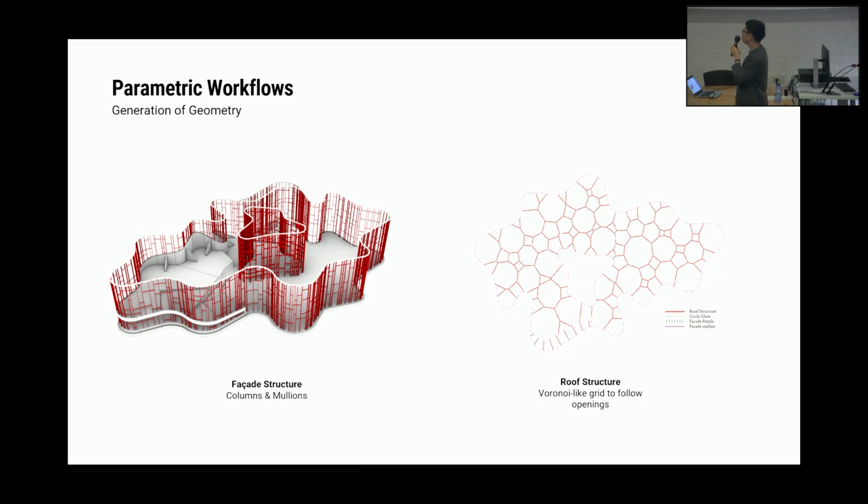Global stability of the structure is achieved through this courtyard area. In the courtyard, where the architects originally envisioned that they would clad it with mirrored elements and could hide structure, we stiffened up and beefed up the column elements and also added bracing elements to brace the entire structure.